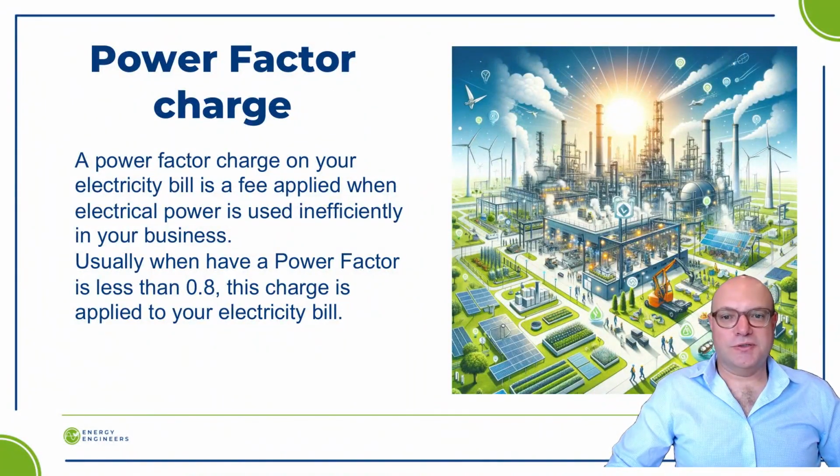Power factor charge. Some of us may be more familiar with this one. What is a power factor charge? A power factor charge on your electricity bill is a fee applied when electrical power is used inefficiently in your business. Usually, when your power factor is less than 0.8, this charge is applied on your electricity bill.